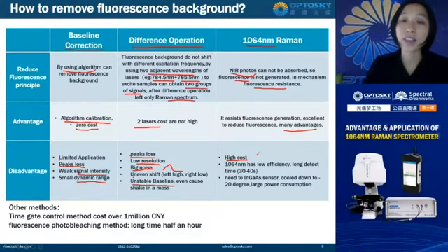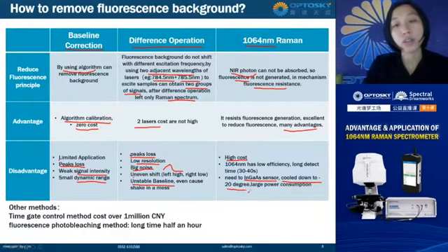Why? Because you need to use an InGaAs sensor. It has to be cooled down to minus 20 degrees to work, and it also generates large power consumption.